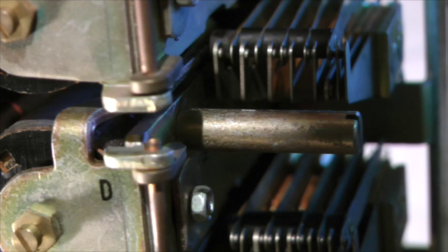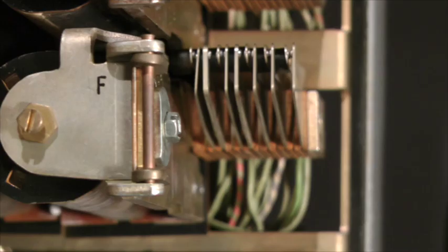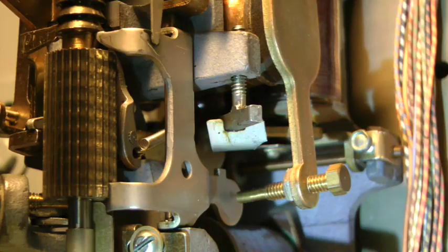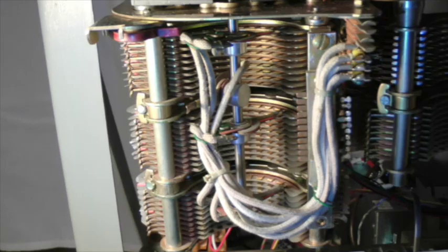The D and F relays are operated, the vertical off normal springs are operated, the shaft and wipers are held in a fixed off normal position by the spring tension of the double dog. The tip, ring and sleeve wipers are connected to the bank terminals of the calling line. The calling line is cut through to the first selector. The line finder remains in this static state until it is released.